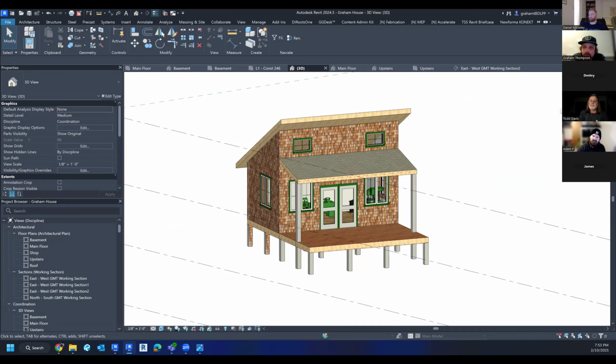The one other thing that you may run into now, depending on how the file was built and who built it, is that what you think is your file, your Revit family, is actually a Revit project consisting of a bunch of different Revit families. Sometimes you experience that where you download a .rvt file. If you can avoid it, try to download only RFA files, which are the individual family files.